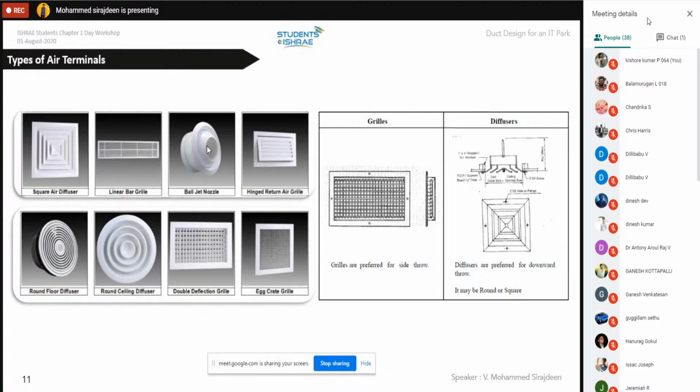In a data center or any electrical control room, for the panels they will lay control cables under the false flooring. In that kind of case, we will have more space under the false flooring. So we can utilize the same false flooring for supplying air by using bottom throw units. In those scenarios, ducts are not required. We can simply pass the air under the false flooring.